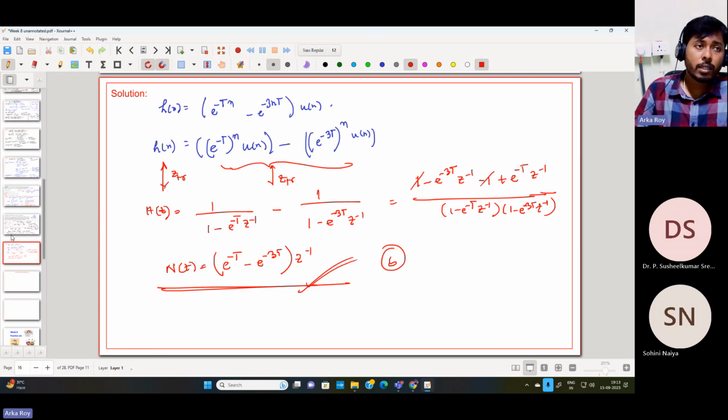And additionally, if the poles of H(s) are in the left hand side, then they should be mapped within the unit circle so that it can ensure stability. And if the poles in the Laplace domain are in the positive side, then the digital domain filter will have poles outside the unit circle, which leads to an unstable filter. So with this, the bilinear transform was covered, and the main theme of this particular week is basically we know what is DFT.